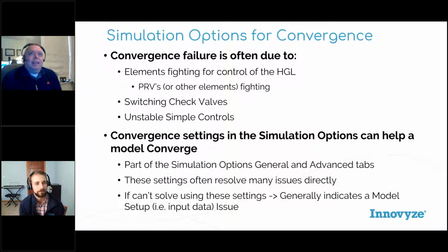I guess, you mentioned pipes near pumps need to have the right direction, but pipes with check valves as well need to have that right direction. Yeah, just the drawing directions, remember. It's going to say that's the only way it's allowed to flow. So you're right. That's one of the few other pipes where direction matters. Most of the time it doesn't, but that's definitely another one.